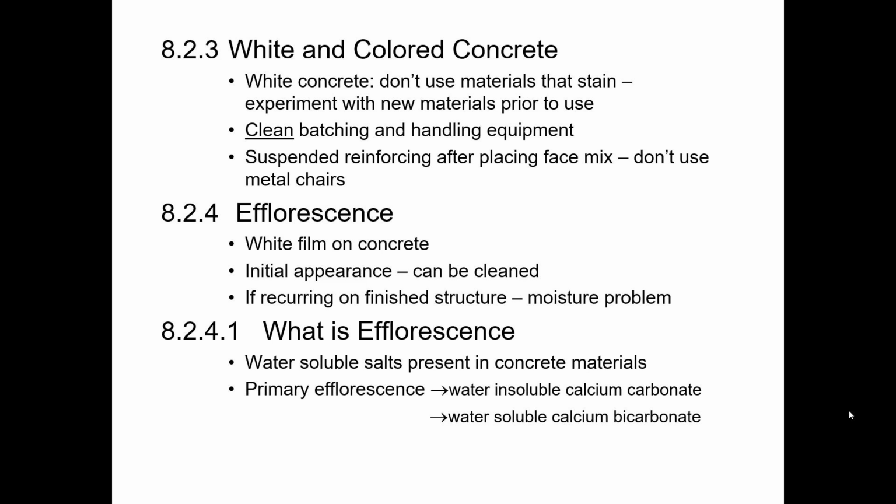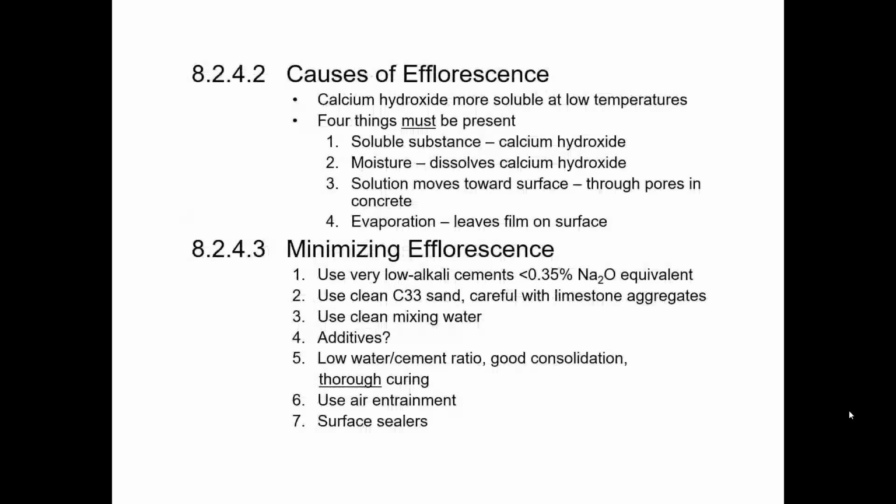Much more common is secondary efflorescence, which is where these calcium carbonates and bicarbonates, these salts, in other words, are in the concrete, but they're not doing anything to hurt you. But if it's a wet environment, you get rainwater or spray from the ocean or something like that, continually making its way on concrete. While it's in the saturated condition, it goes into the concrete, and then as it dries out, it pulls those salts out with it. So that's secondary efflorescence.